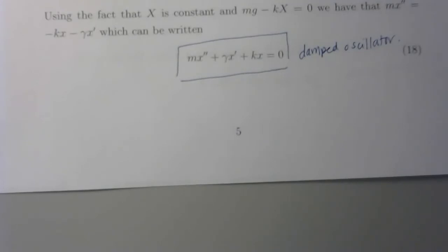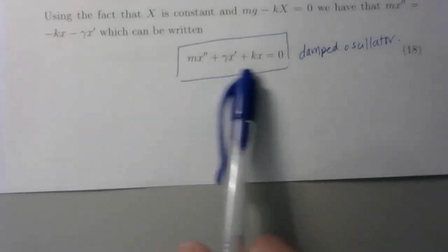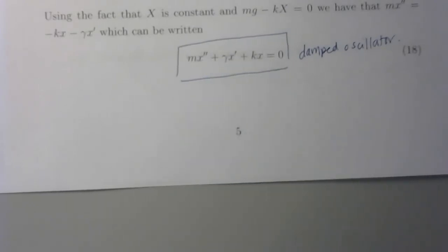Because you can have a very strong damping force, so that when you displace the mass, pull it and let it go, there's no oscillation. It just zooms back to the equilibrium position and stays there. Or you could have really weak damping, and so you get very long sustained oscillations. It takes a really long time to die out. So you can have different kinds of trajectories for the system just by changing these gammas and k's.